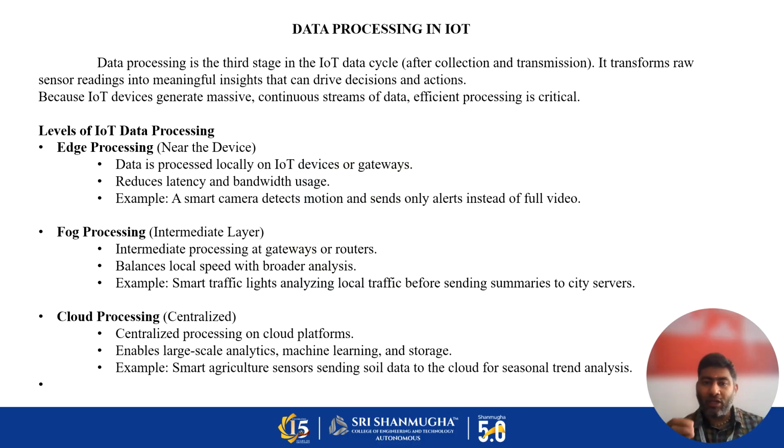Let's say you have put a logic in your cloud: if my moisture value gets below 60%, switch on my motor so that the pump will allow water to my field. The moisture in my field goes up. So initially data is collected and sent to your cloud. The cloud will compare the value and then a signal will be sent to your motor. The motor switches on and your field gets water.